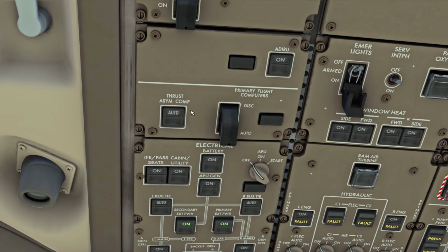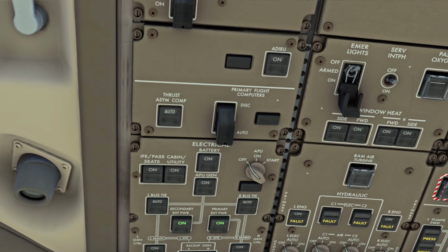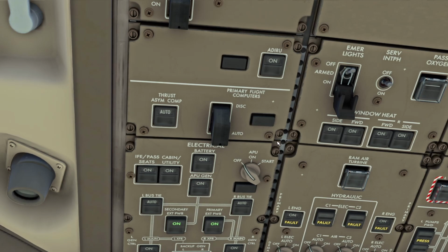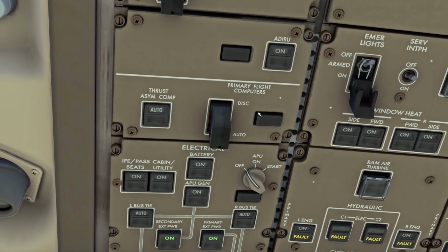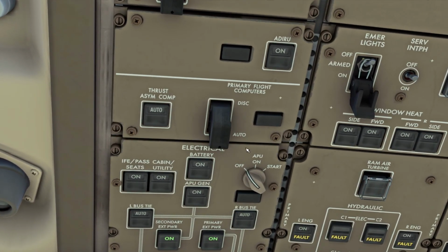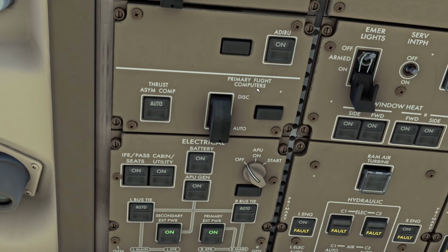It's very important to have, and the primary flight computers, every control input basically that you give on the yoke runs through the primary flight computers. Also enables use of things like the autopilot, auto speed brakes, etc. It's the core system of the electronic flight control system, or the fly-by-wire system on board of the airplane. So only in non-normal situations you would deal with these switches. So leave it all on auto, and just make sure that everything works accordingly.